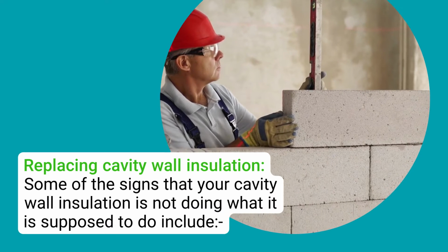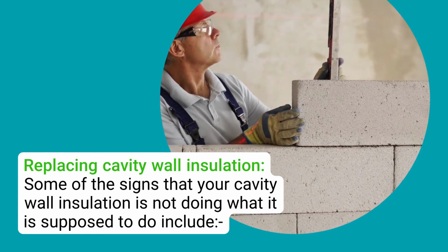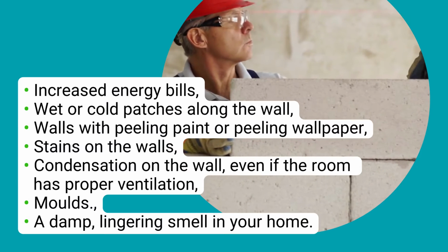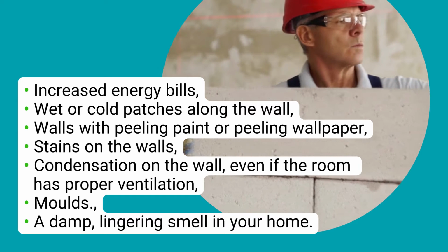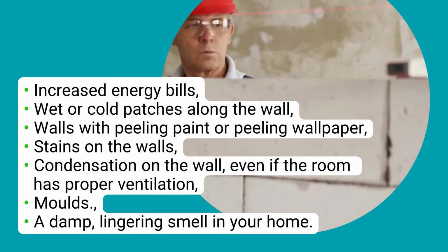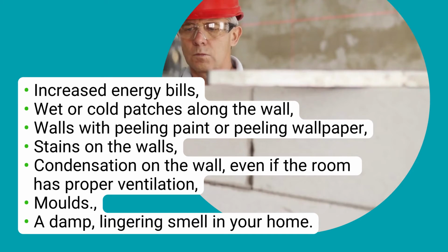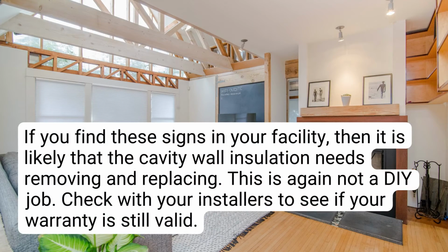Replacing cavity wall insulation. Some of the signs that your cavity wall insulation is not doing what it is supposed to do include increased energy bills, wet or cold patches along the wall, walls with peeling paint or peeling wallpaper, stains on the walls, condensation on the wall, even if the room has proper ventilation, molds, a damp, lingering smell in your home. If you find these signs in your facility, then it is likely that the cavity wall insulation needs removing and replacing. This is again not a DIY job.